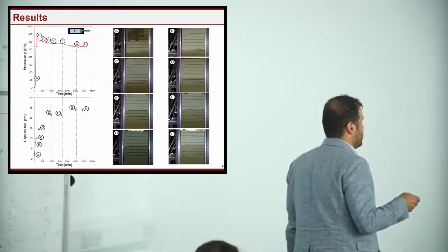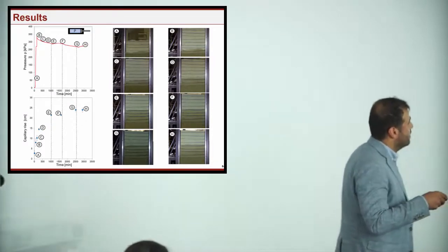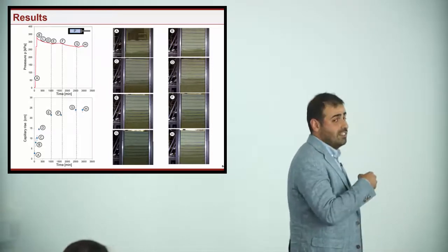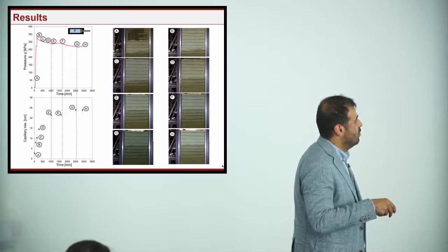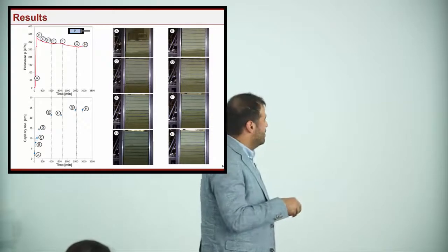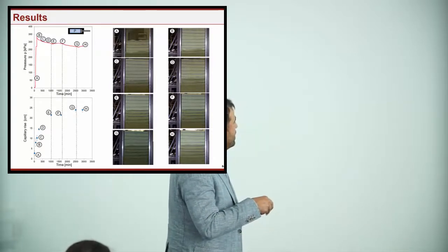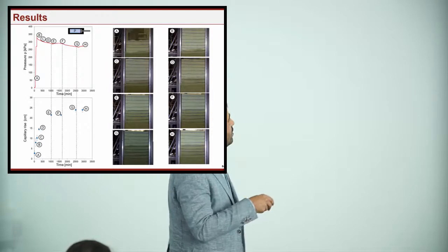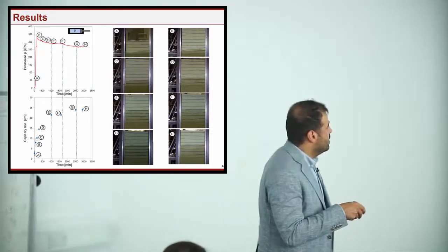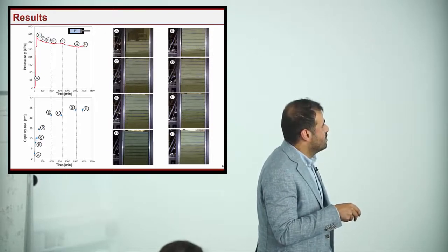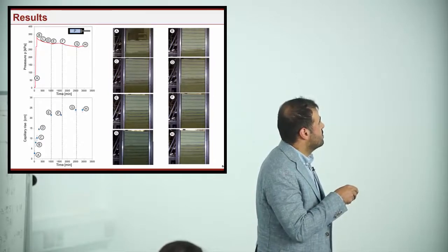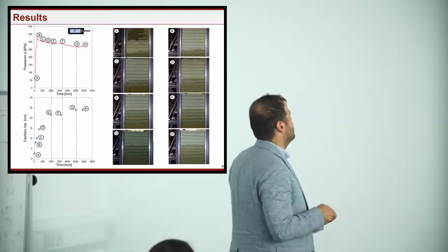What is really important, I was really surprised to see this result. Here you can see during the filling the increase of the capillary rise. I was controlling the level of the groundwater table, which reached almost half of the retaining wall. And you can see that there seems to be a correlation between the increase of the capillary rise and the reduction of the pressure behind the wall. Especially here between the points E and F, you see that there was no increase of the capillary rise. The same was recognized here in terms of pressure, which seems to stabilize.